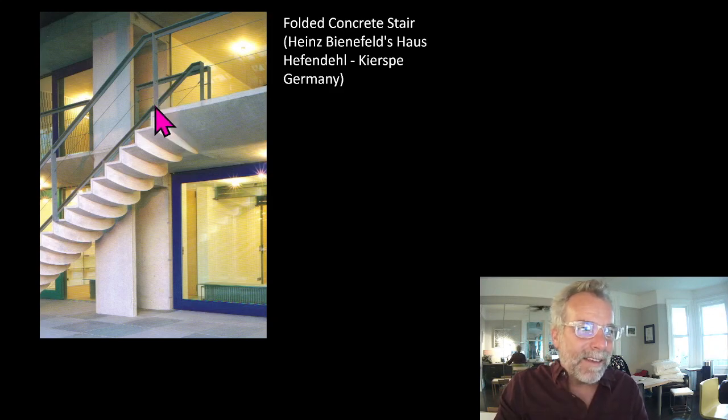So in this case, the architect knifed the steel into the side of the concrete, and the anchorage would have happened inside the concrete, not on the face. Problematic from a sequencing point of view. This doesn't fall into the normal workflow. Normally the concrete is cast and the metals come in afterwards. So this needs real commitment and coordination. That's slightly unusual.